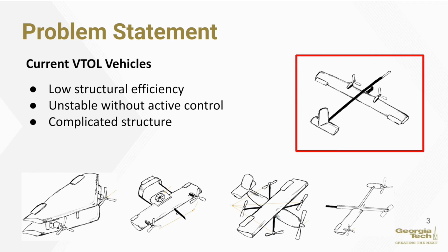In this project, we aim to develop a multi-purpose unmanned aerial vehicle that can achieve VTOL in different terrain. For those who don't know, VTOL means take off and land vertically without a runway. There are indeed many other aircraft that can achieve VTOL now, but they all have mechanisms dedicated to achieving the flight transition, like rotating rotors or extra motors, which are all dead weight when not used. Thus, we want to overcome this and improve the structural efficiency in our design.